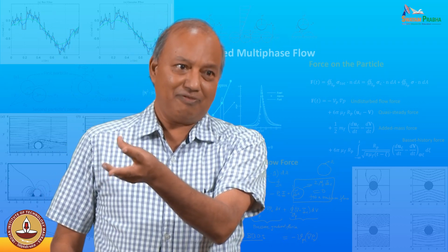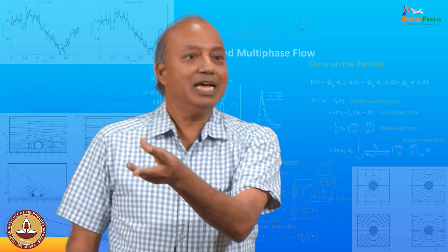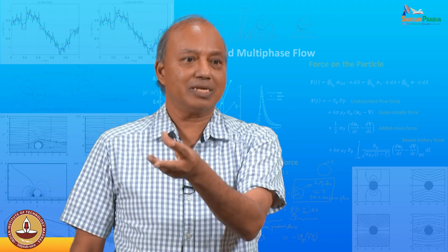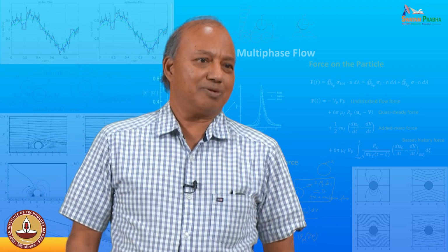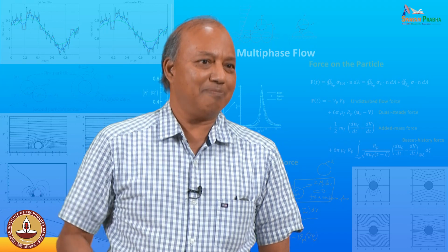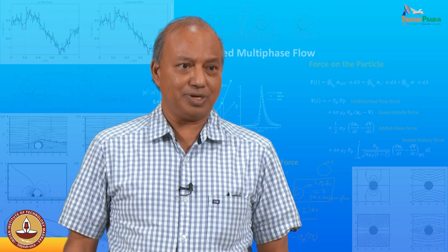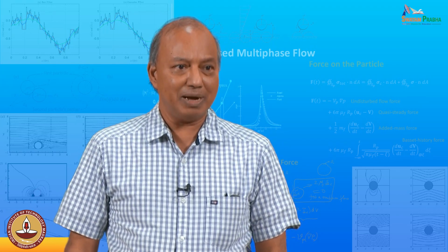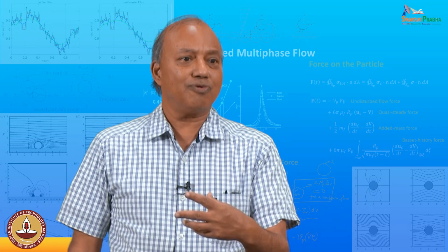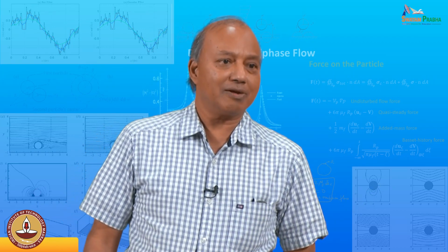So, it can be a very useful thing for PIV, especially in high speed flows, because it's very hard to make the particles smaller and still have a measurement. So, this is an important issue in high speed PIV measurements: how do you get the true fluid velocity from the particle velocity? Yeah.